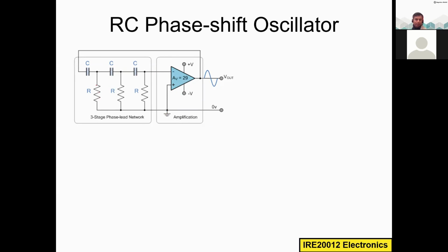Of course, every resistor or RC network must be grounded on the other side in order to complete the circuit and have current flow. Definitely this operational amplifier will give another 180 degrees, so we get 360 degrees at the output.